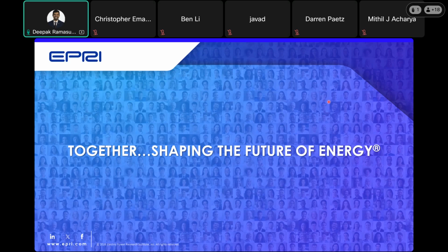Those would be additional aspects that have to be considered when doing a sizing. In that particular case study, there was enough active power reserve resources available across the network. So the main sizing was to look at voltage strength and stability across the various loading profiles.